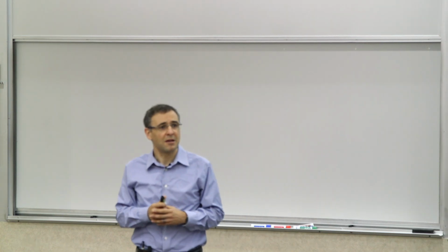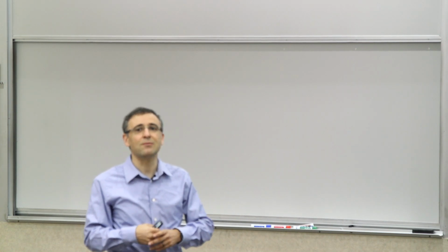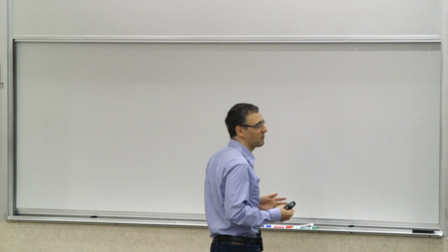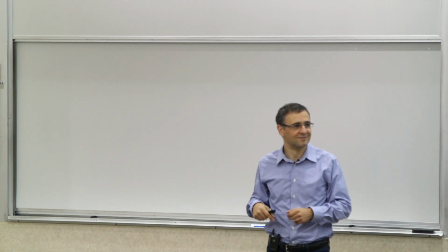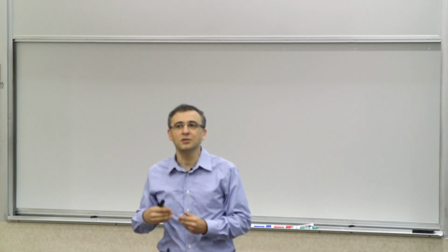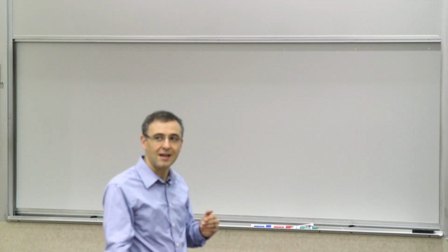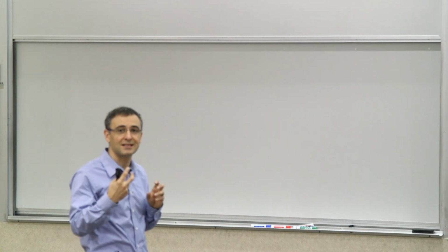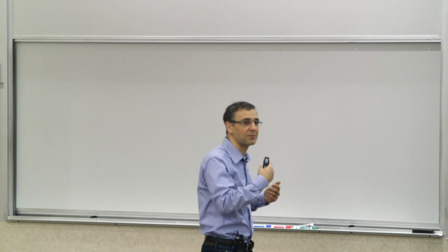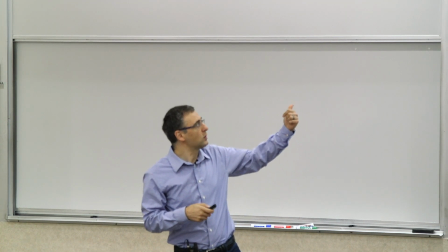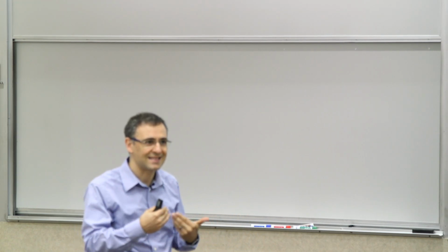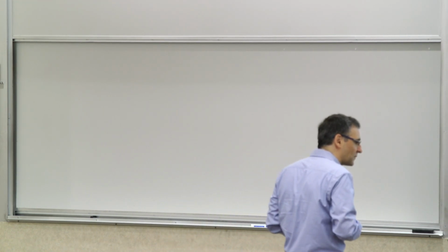Now, let's say you're using very small scale CMOS transistors, with a breakdown voltage of like 1 volt. Then if you are trying to deliver the same amount of power, you will have to operate more on the left, which means you need to operate in situations, and we'll discuss this in a lot more detail in practical settings, where you need to produce large currents and small voltages. And that scaling matters, the way you think about that. Okay.